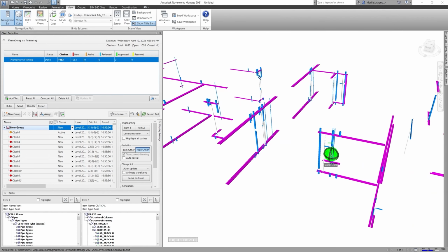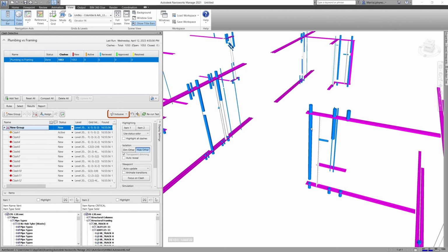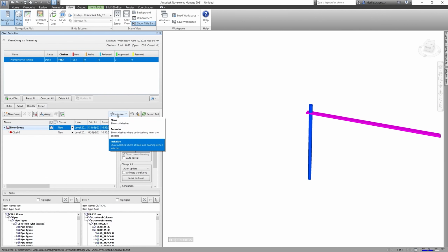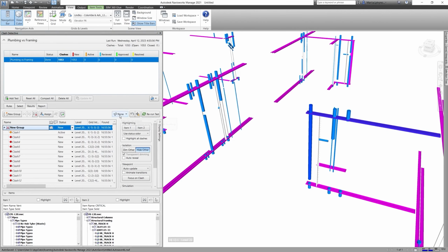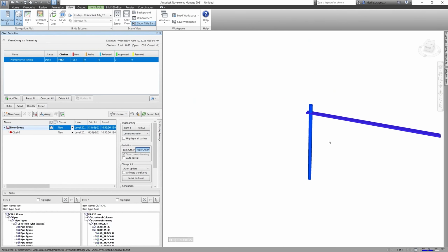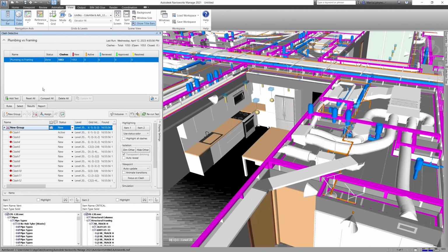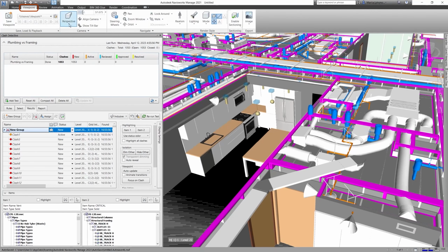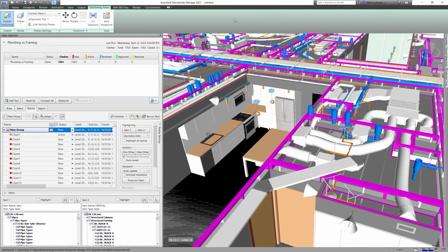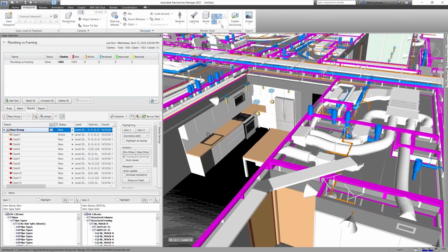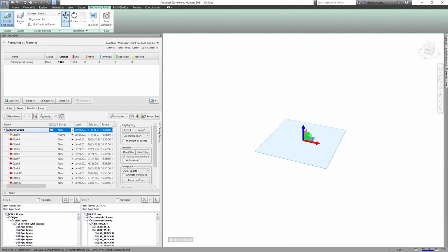There are also a few filters for clashes that help you with selecting proper clashes or objects. None. Turn off filter by selection. Exclusive. Only clashes involving all of the currently selected items will be shown in the Results tab. Inclusive. Only clashes involving at least one of the currently selected items will be shown in the Results tab. To enable sectioning, go to Viewpoint tab and click Enable Sectioning. You can create viewpoints for clashes or outstanding areas in the project.